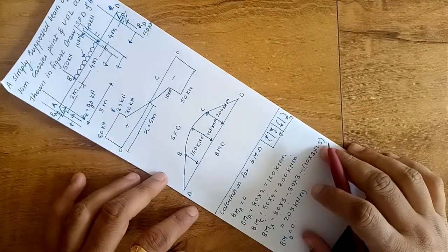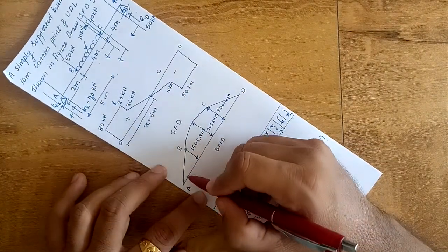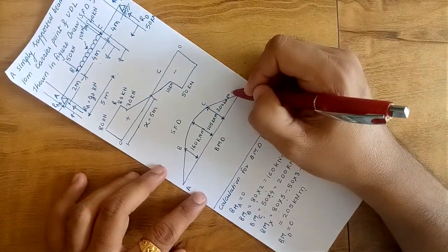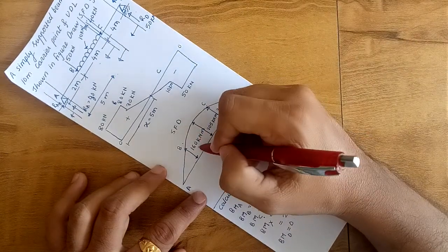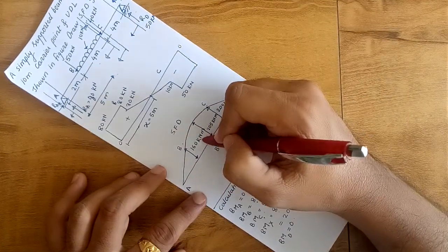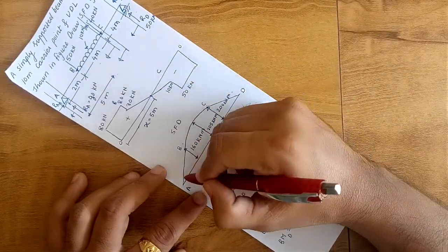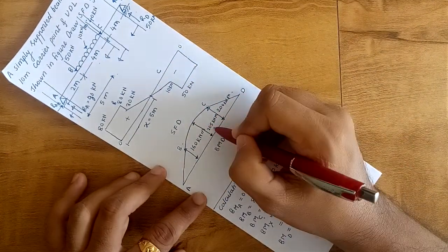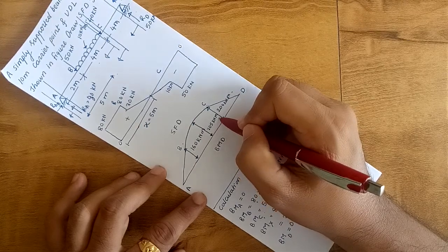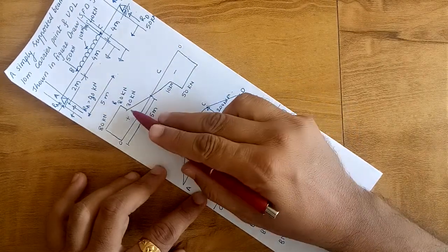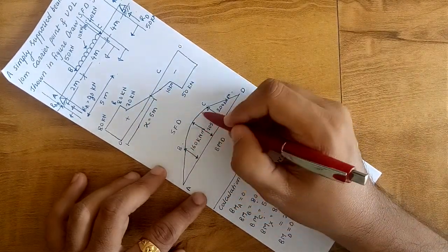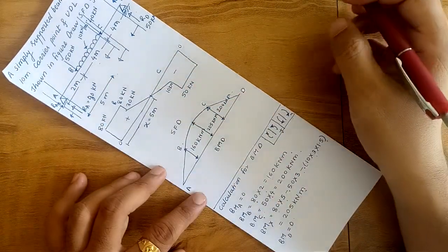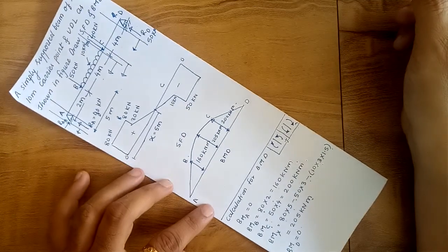Now, how to draw the bending moment diagram: this is the reference line, and I got at point C 200 kilonewton meter moment, and at point B I got 160 kilonewton meter moment. So I have plotted these points and drawn a straight line because it will be a straight line variation, and at point X there will be the maximum bending moment, that is 205 kilonewton meter. Okay, and it is an inclined line, so there will be a curvature like this. So this is the point of maximum bending moment. This is how we have to solve this problem.